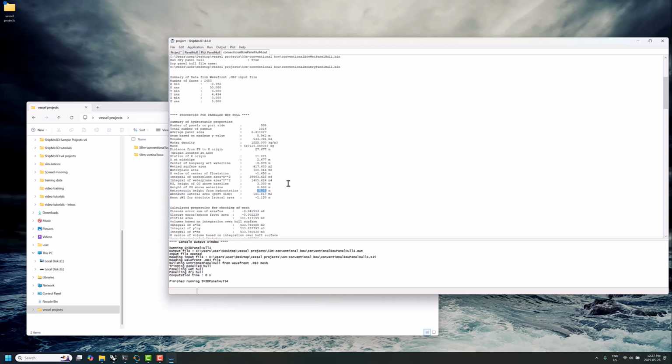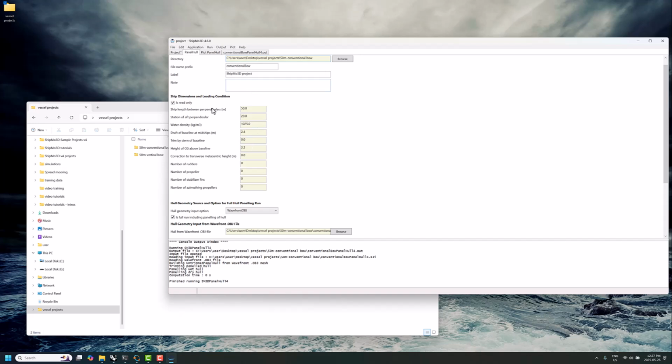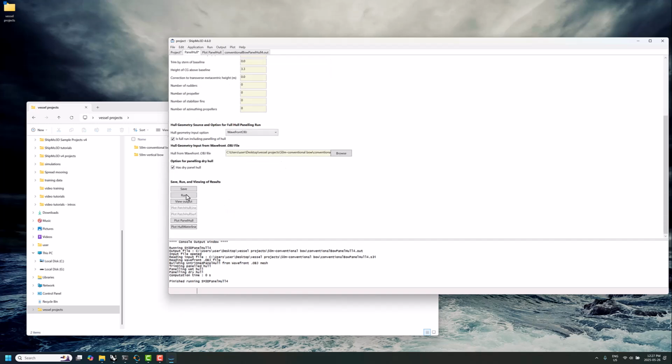So this is kind of making sure we have the same kind of roll restoring stiffness, at least onset stiffness. So I'm happy with that. I was playing with this beforehand. If you needed to make an adjustment, you can make that here and just adjust the number up or down a little bit to get it closer to what you want it to be. But we're good with that for now.